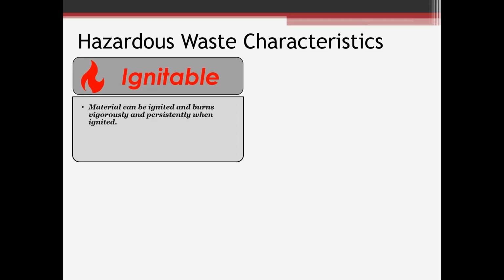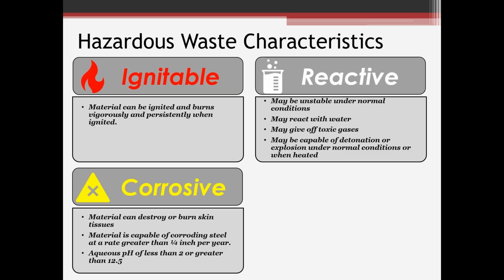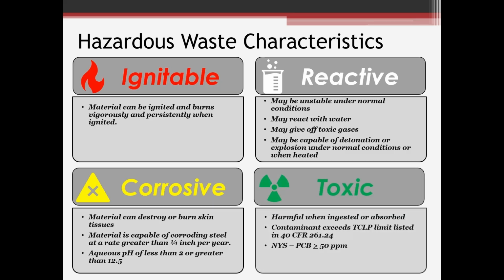All right, so hazardous waste. We have something that we know is being disposed of. What do we have for hazardous waste characterization? There are 4 criteria you want to look at as far as hazardous waste characteristics. One being if something's ignitable. Obviously, we don't want that going into a landfill. If it can spontaneously ignite, a regular landfill is not equipped for that, and you can have quite a mess on your hands. That should be going to a facility that can handle, treat, dispose of, and manage those materials.